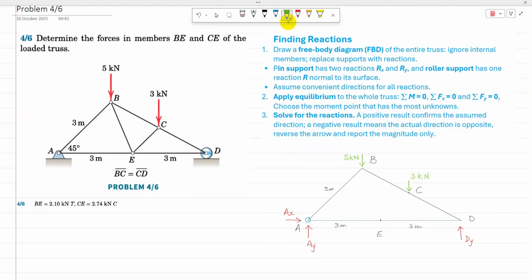But the line of action of the 5 kilonewton is going to act here. We don't know the distance, so I am going to map that point as B dash here, and then map that point here as C dash. Actually required are the distance from A to B dash and the distance from A to C dash. To go further, I can use the similar triangles rule.